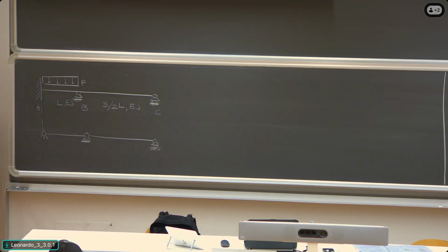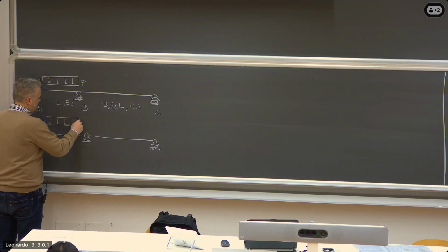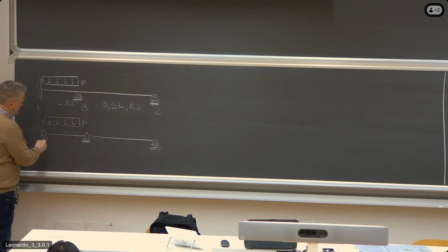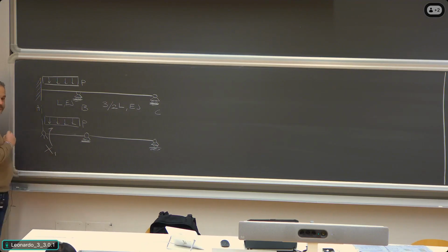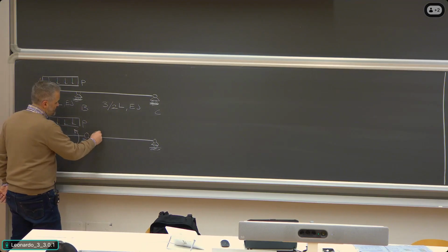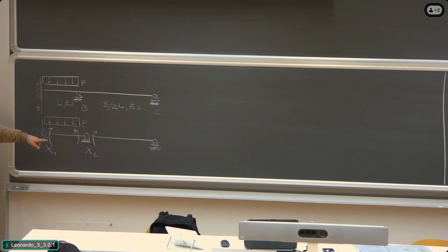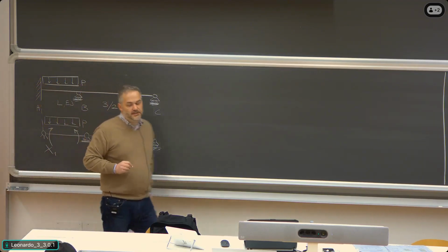So changing the structure in this way, then of course the static load is still there, means my two unknowns are one bending moment here, call it x1, and an internal bending moment here at support B, call it x2. Note the difference between the two bending moments.